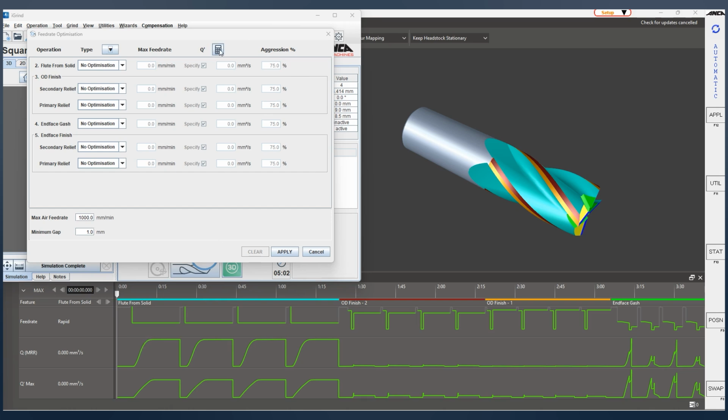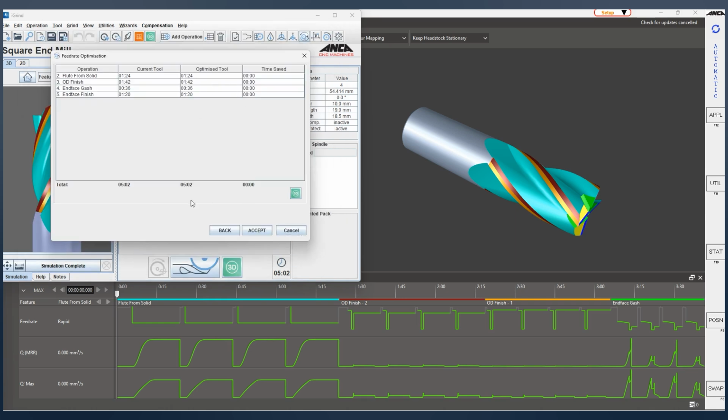Now this reverse calculator, what this does is, if you already know the wheels that you use and what the Q prime is, or you already set the feed rates for your wheels in the factory, then you can reverse calculate this. So if you hit this button, based on your feed rates already in the TOM files, it's actually calculating the Q prime, and then you can use that so that you don't have to worry about asking the wheel supplier what the Q prime is, and that's why you are not seeing any cycle time improvement, because you are reverse copying that Q prime.